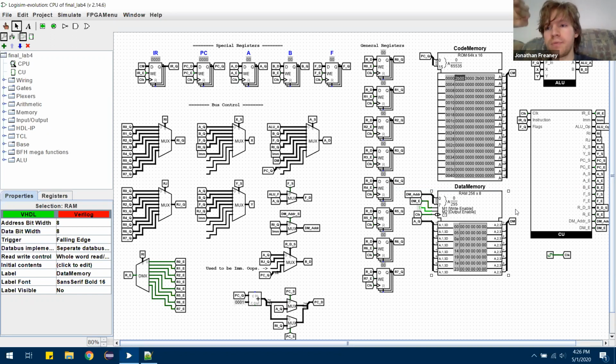So until we went up, right as we went up, that's when it would trigger and change. But at the same time, something else was happening in the CU that made it so that the destination for the results being loaded from there was being changed as well, and so it would end up not loading everything correctly. And Ethan fixed this by simply changing the trigger from the rising edge to the falling edge of the clock. So it just had to be slightly out of sync, but that actually fixed it entirely without disrupting anything else.